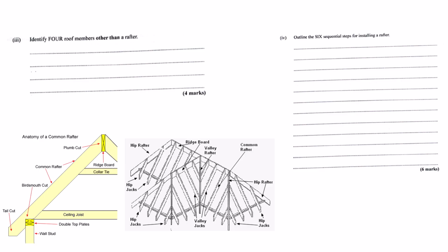That's the collar tie. This is another horizontal piece. But this one connects two opposing rafters somewhere higher up, between the wall plate and the ridge. Tying them together across the span. Precisely. Its main function is to stop the rafters from spreading apart at the bottom. Like under wind load or the weight of the roof itself. Exactly. Stops the roof pushing the walls outwards. Keeps the triangle shape rigid. So ridge board, purlin, wall plate, collar tie, along with the rafters, each playing a specific role. Makes for a strong, integrated structure.